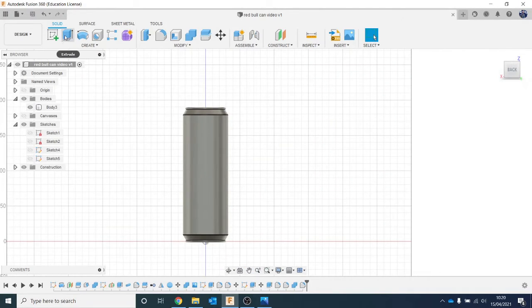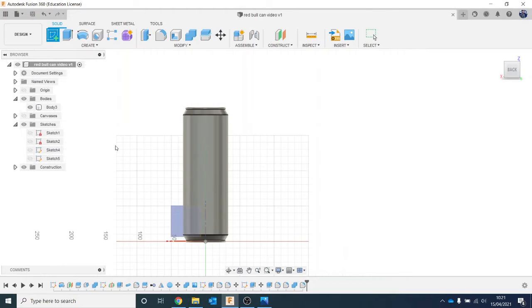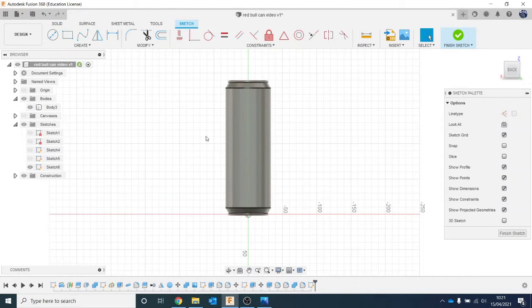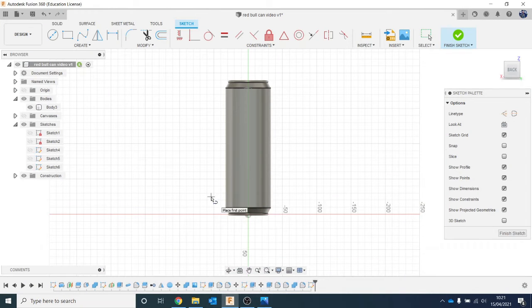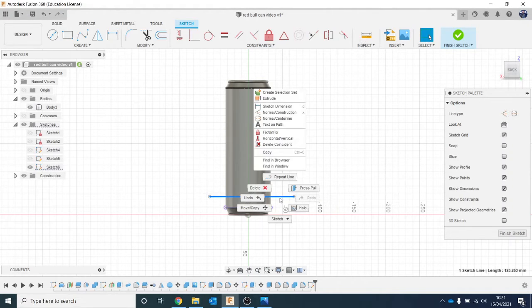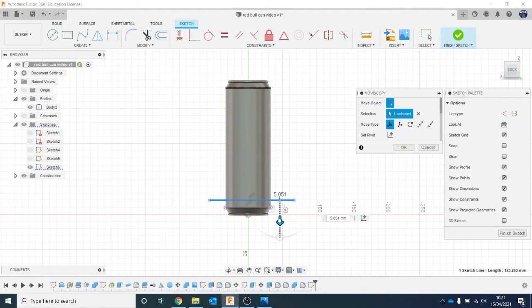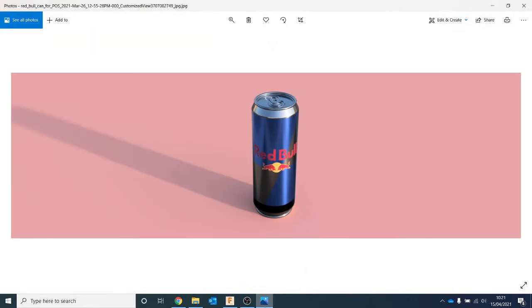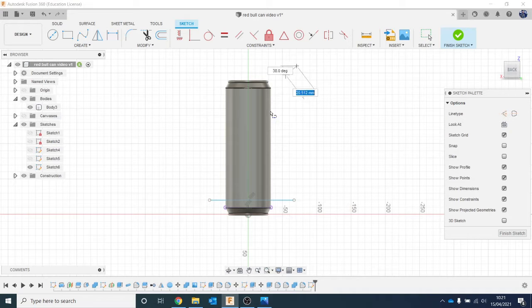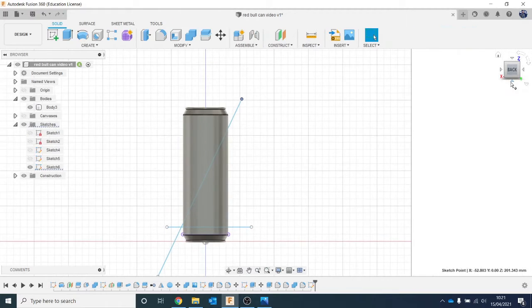So let's come across here. Let's create a sketch on this plane. I'm going to do a couple of lines, hit L. First of all, if you have a look, we had just a line coming straight across, so let's just do that one. That's a little bit high, so let's just right click and move and bring it down just a touch. And then last time I found this quite a bit fiddly, just trying to get the right angle of the line really, so let's just sort of come across like that, and then let's see if we can move there. I'm going to hit OK.